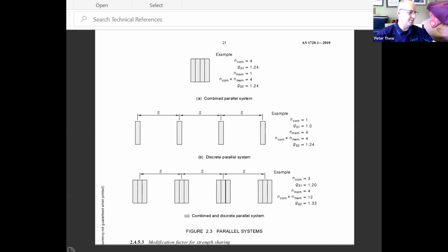So, if I can labor the point a bit, when you have one piece of timber like this, if you have a knot, then the knot goes all the way through the whole member. In an LVL, when they put the laminates together, sure, there's a knot there, but it's only in one of the 20 laminates. So it's only 1/20th of the way through. So you've got 19 pieces with high strength there.